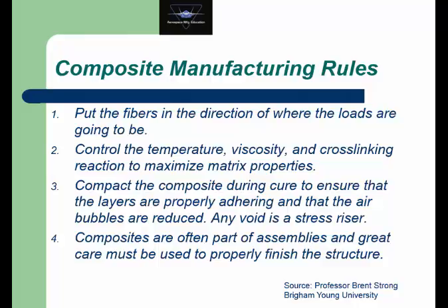And it's very important that we get a complete wetting of the fibers. We want to have the resin flow around the exterior surface of the fibers and to form a close and intimate mechanical bond with the fiber as the resin cross-links.